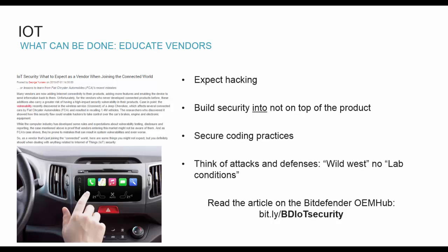Second, security must be built into the product. This means that your product should expect to work in a hostile environment. You should vet all the input instead of blindly trusting it, and trigger a proper reaction when incorrect values are received. For example, if your speed sensor indicates a speed of 32,000 miles per hour, then the onboard computer should light up something like a speed sensor failure message and not show the speed of 32,000 miles per hour, or even worse, just crash altogether.